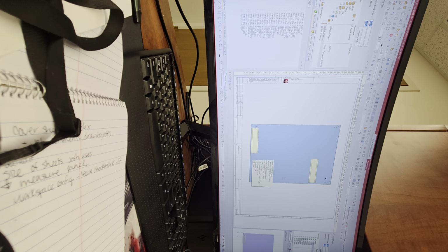So this next piece I want you to do is right click on this rail, initiate the move command. So click on the move object once. Once you click on the move, you'll see the outline of your placement. And when I do this myself, if I know that this needs to be, let's say 10 inches from the bottom, 1 inch from the left side, I pre-move this, without placing it, as long as you're just moving it, it's okay.